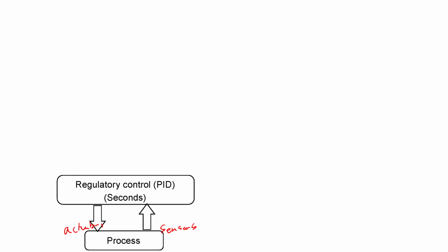These actuators and sensors will communicate back and forth with a control system. We have simulated control systems using PID controllers. This layer here would often be called, again, your DCS, or your distributed control system. The DCS is the thing that is reading in these signals, which are typically electrical.